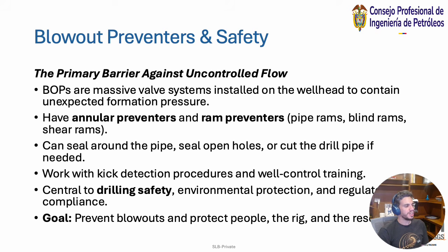It's basically your most important part against any uncontrolled flow. It blocks anything from coming back out that you don't want to come out. They are massive valve systems installed on the wellhead to contain unexpected formation pressure.